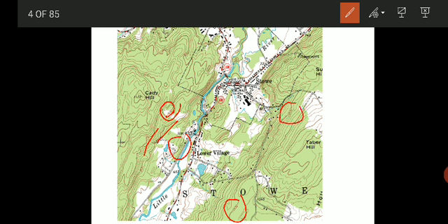So what is a contour? A contour is an imaginary line which joins points of equal elevation. Throughout this line the height remains the same, that is the height above the mean sea level remains the same. These contours will be rounded or oval in shape, or however the topography of the ground is, the shape of the contour will be.